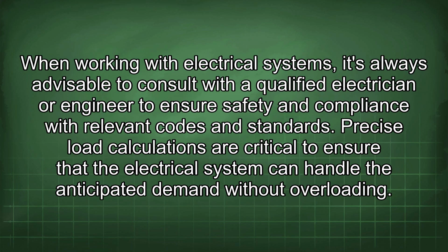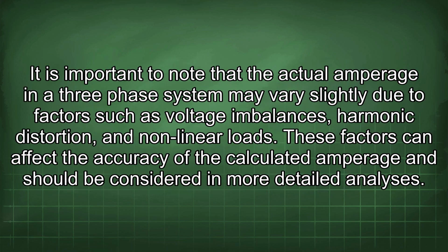When working with electrical systems, it's always advisable to consult with a qualified electrician or engineer to ensure safety and compliance with relevant codes and standards. Precise load calculations are critical to ensure that the electrical system can handle the anticipated demand without overloading. It is important to note that the actual amperage in a three-phase system may vary slightly due to factors such as voltage imbalances, harmonic distortion, and nonlinear loads. These factors can affect the accuracy of the calculated amperage and should be considered in more detailed analyses.